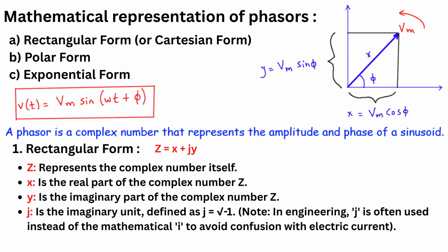Think of a spinning bicycle wheel. Angular frequency measures how many radians, or how much of a circle, the wheel turns through every second. A higher omega means a faster spin and a more rapid oscillation. It's directly related to the frequency f you might be more familiar with, which is measured in hertz. For the 60 Hz power in our homes, the angular frequency is about 377 radians per second. As time t marches forward, the term omega t continuously increases, driving the wave through its cycles.